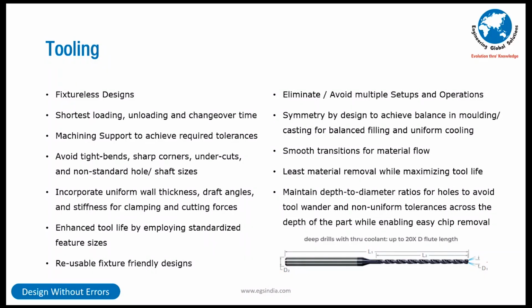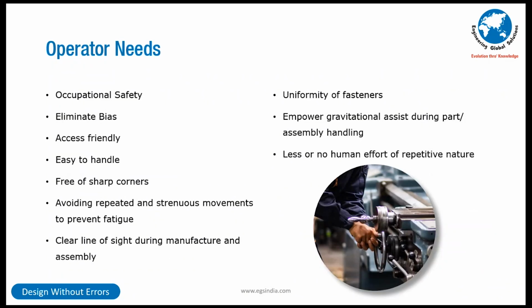Maintain the depth to diameter ratios. Your software already has all these rule books sitting inside. You can put them into your DFM Express. It's there. You can put it in so that the tool does not wander, you don't have non-uniform tolerance zones coming up, and also for easy chip removal. Then the operator needs, I need to look at from a design point of view. Sir, you are asking every one of them to be looked at from a design point of view? Absolutely. If design can fix it, so much grief down the line can be dispensed with.